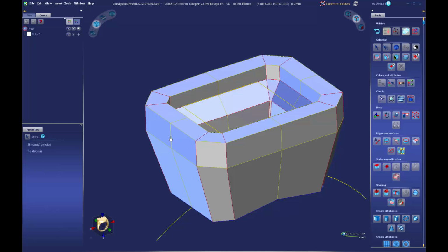In an edge mode, this section here, if I grab this edge and do an edge ring, what I'm going to do is split it using the same split and pull. And I'm going to move my tool up towards the corner. We call this a constraint edge. By putting one on either side of the corner, we get a fillet look. We could have used the fillet tool, but that can get a little messy around corners. So be careful with the fillet tool.